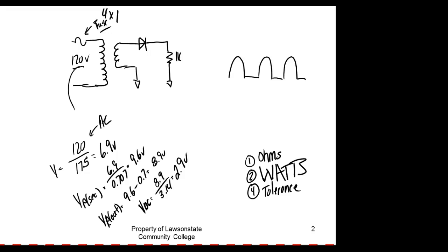So I know what to expect now, right? I mean, if you don't know what to expect, of course, there's very little that can go wrong with a half-wave rectifier. What would I get out if the diode opens? If the diode opens, what voltage would I get across my resistor, which is my output voltage?